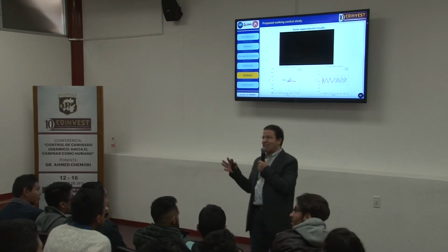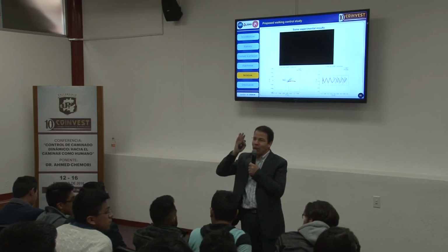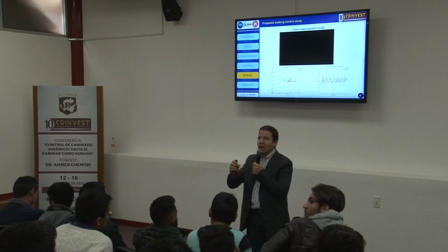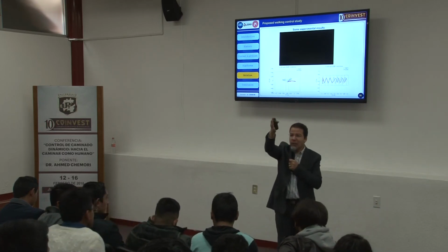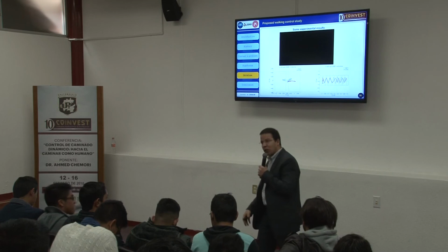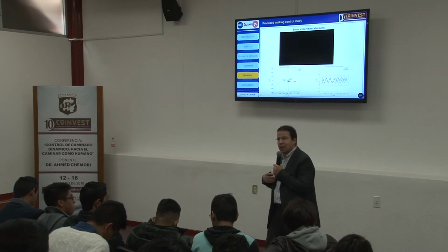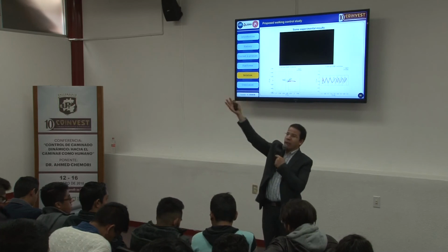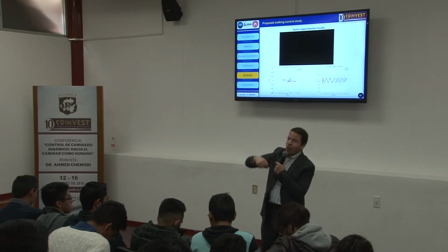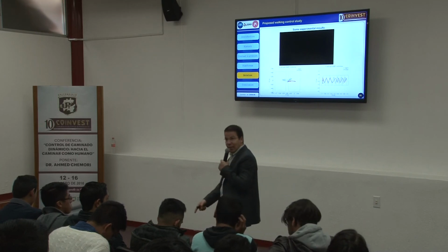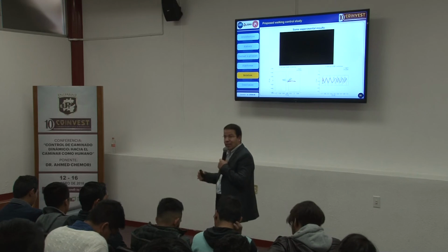I think each kind of system has its specificity. For both, we have very challenging problems. The very challenging problem in humanoid walking is the hybrid aspect. It's this contact with the ground. It's the stability, because we cannot easily keep the stability. If you have a robotic arm, the base is fixed. He will not fall down. But here, the contact is unilateral. He can move in this direction, not the other direction. So at any time, he can fall down.